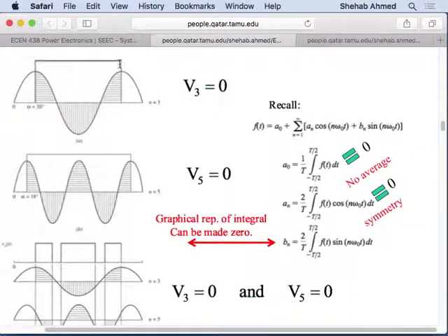My pulse multiplied by the sine is going to be 0 here and 0 here, and equal to the sine where the pulse is. Assuming this pulse has a maximum value of 1, then your output will be equal to the sine wave during this period.